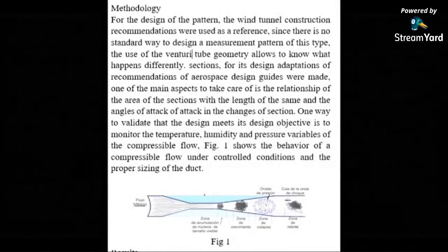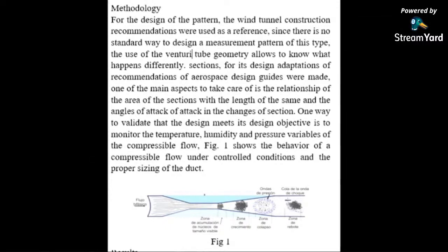technique. An important part for the measurements carried out in this laboratory to be reliable is to have a measurement standard that can be calibrated and is a reference for the calibration of the measurement equipment and to be able to guarantee the measurement in all possible cases. The measurement standard necessary for this task must allow knowledge of the fluid and control of the behavior of the flow, the conduit that will be used as a standard. The most suitable way to have this characteristic is through a venturi duct.